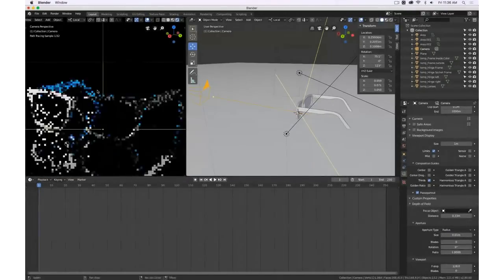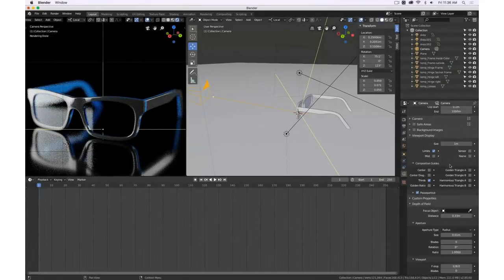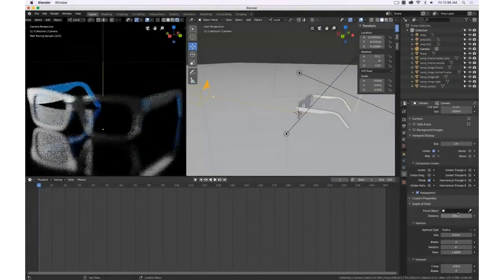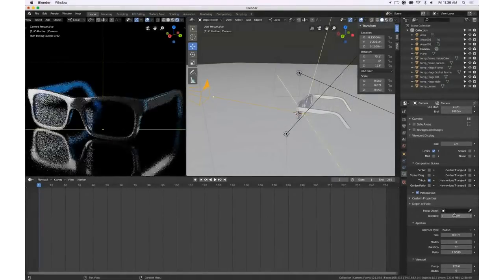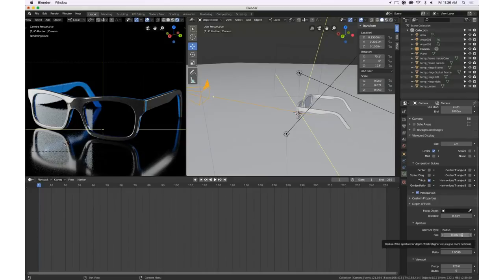Yeah, way too strong. And again, here with the limits, if I now play with the distance, you can see how I can set a focus to parts of my object. So maybe 3 millimeters. What about that? Too strong. 2 millimeters. So you see, these values I didn't find in a book. I simply tried to pay attention to what happened in my rendering when I was adjusting these values. So I made an artistic decision.